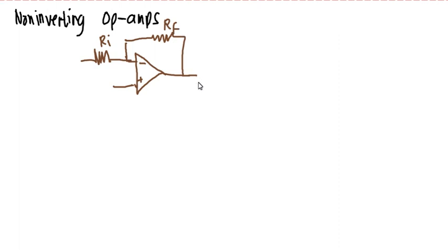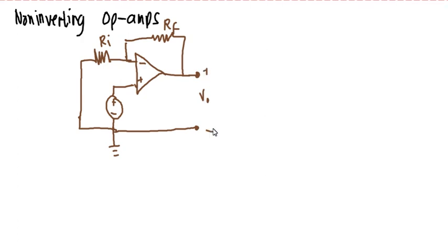Okay, here we are not taking our output. Since it is non-inverting, it automatically goes straight to our ground. This one, we feed the signal, since it is non-inverting, your signal is at the positive. So this will be connected to the ground. Okay, then we take our voltage output. This will be positive, this will be negative.